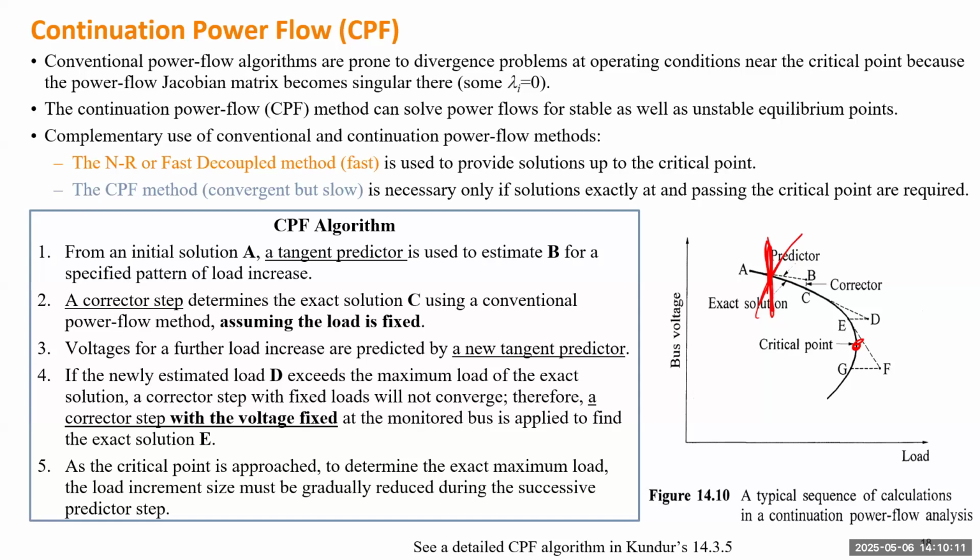But some engineers still want to see what the bottom part looks like, right? Then you assume this load model. This load model doesn't exist in the real world. It only gives you a complete PV curve. So the purpose of drawing the complete PV curve is not to utilize any part on the bottom for operation, because it doesn't make any sense. The purpose is really to help you get an accurate estimation of where this critical point is.